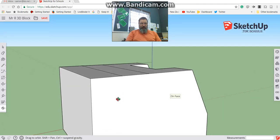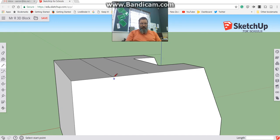And I'm going to orbit around to the other side of the block. Go to my end point here. Draw a line straight down. Type 10. Press enter. Again, the line is still attached. Make sure the line I'm drawing is red. Type 10. Press enter. And I'm going to go back up. And I can type 10 and press enter again, or I can just go to the end point. See how that line is still blue?